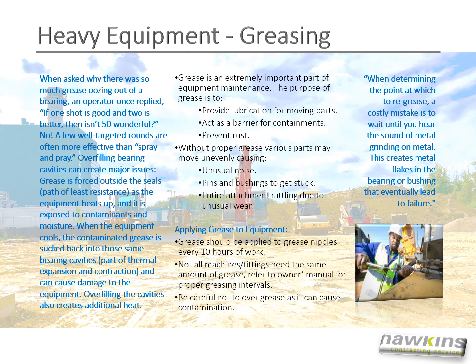To apply grease to the equipment, grease should be applied to the grease nipples every 10 working hours. Not all machines or fittings need the same amount of grease. Refer to the owner's manual for proper greasing intervals. Be careful not to overgrease as it can cause contamination.